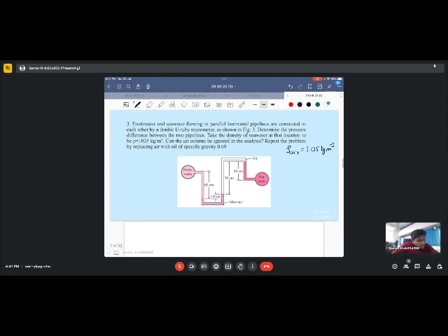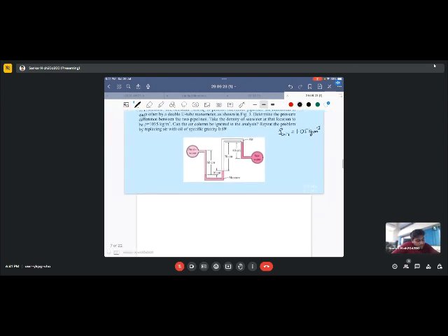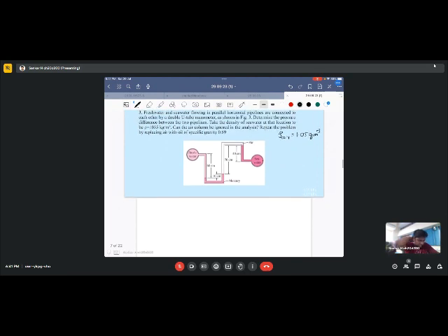Let's come to the second part of the problem after we have completed here. So as I was telling before, we start with one part over here. Whenever we are going down, we add the pressure, and whenever we are going up, we subtract the pressure. Whenever we see that the levels over here are matching, we generally disregard that. So the mercury height from here to here and here to here are disregarded. Similarly, air pressure from here to here is disregarded.